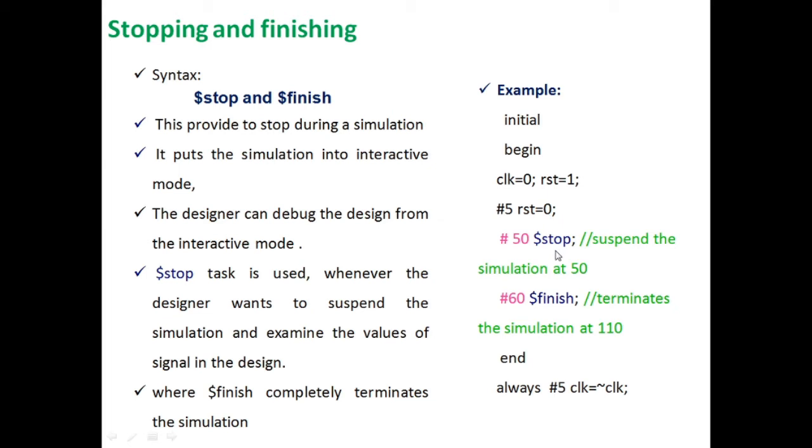Okay, good. That means as $stop, here I am suspending the simulation at 55 seconds. At 55 seconds, it should be not 50. And as $finish, that means 55 plus 60, 115, I am completely stopping the simulation. This is the difference between $stop and $finish usage.